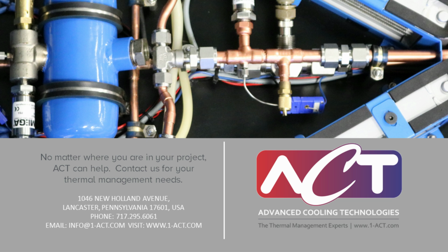As you go very cold, you'll start getting into ethane and methane temperature ranges, or even lower, you're starting to get to helium. You get really hot, and you'll start looking at sodium, potassium, those types of working fluids. And for all those situations, a lot of thought needs to be put into the material compatibility. So making sure you have the appropriate envelope selected is very important.